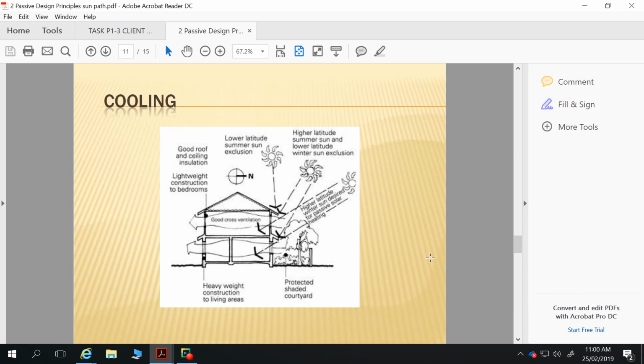There's the avenue within the NCC to allow you to get an energy rating for your place by reference to another building which is comparable, and that comparable, that's a grey area that gets interpreted, etc. And sometimes people go, well, we've built that exact same floor plan somewhere else. We've got that energy rating. Let's apply that here, even though they might be turned around differently and things like that.